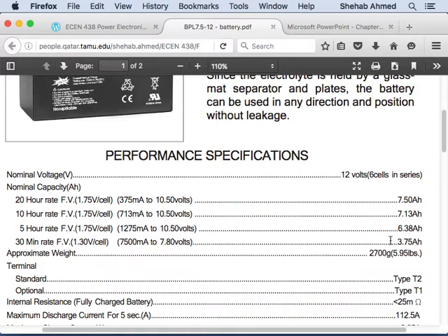It will not explode, right? So even though this battery is 7.5 ampere hours, if you consume this power over a 20-hour period and then try to consume it at a faster rate, the battery will not blow out, but the battery life will degrade. So instead of lasting for 2 years, it will last for a year. And it's not a matter of time, it's a number of charge-discharge cycles.